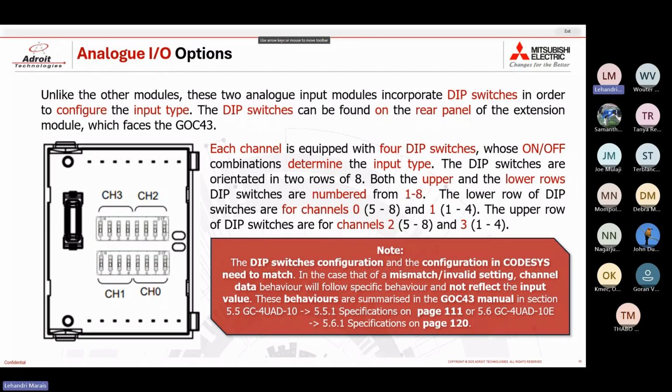You still need to do that, and your dip switch configuration needs to match the configuration in CODESYS. Otherwise, there are certain outputs that will be output in the case of a mismatch or invalid setting,